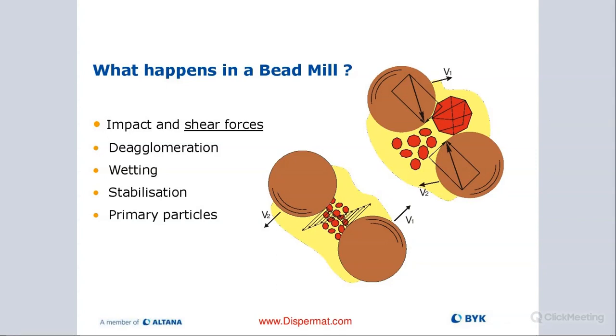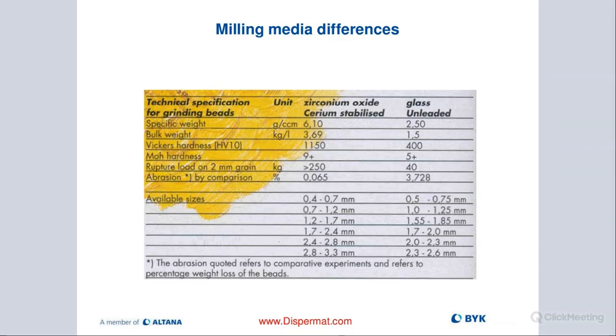He's one of the most renowned milling experts out of Germany, University of Braunschweig, and he has studies and very complicated equations that detail exactly what happens in the mill and the improbability of an actual particle getting destroyed by impact because of that fluid dynamic motion that's going on and pushing the particles away. So that's what's happening inside of the bead mill.